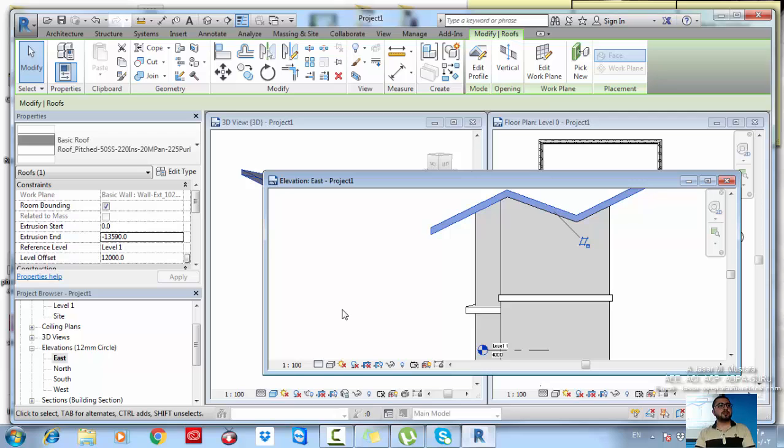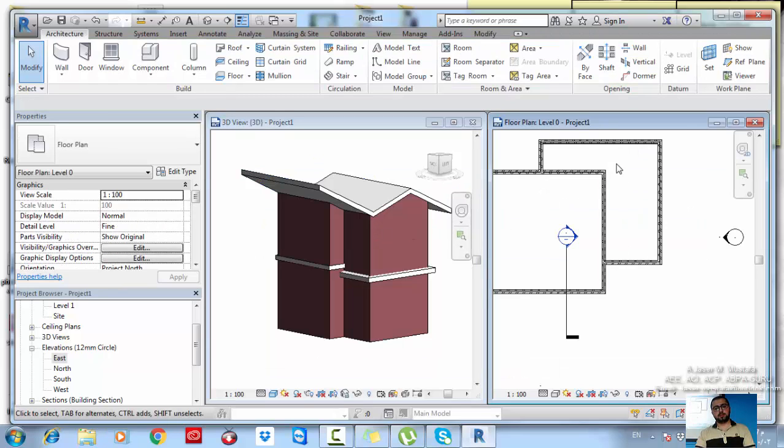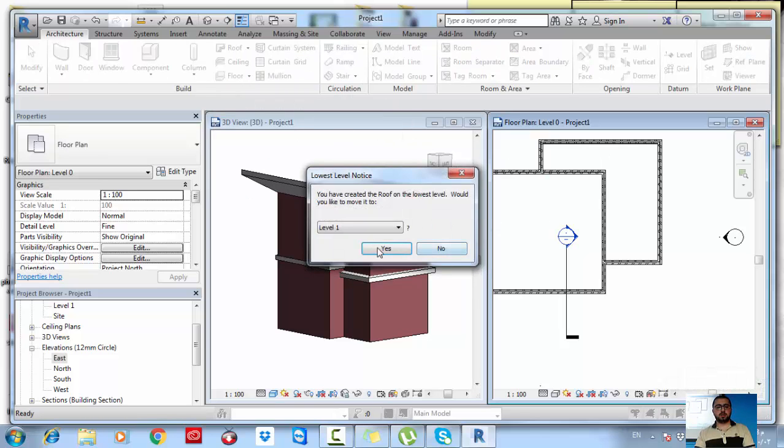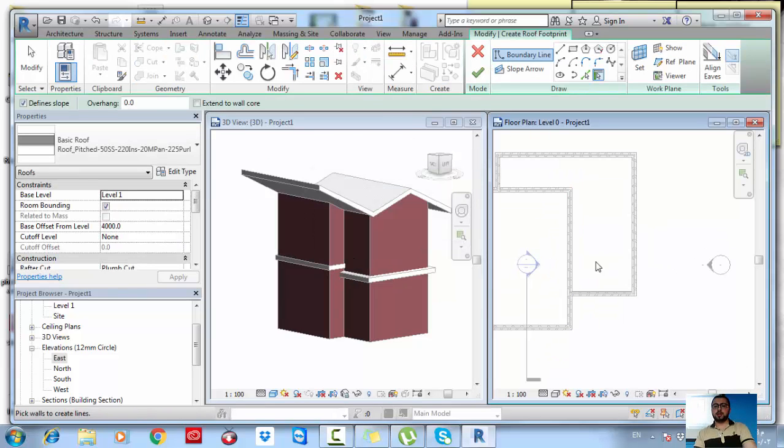Yes. If this 4 angle, I don't want this one with an angle, can I remove the angle? Can you draw something? You want 3 surfaces inclined and one is... There's here on your sample before, you have this L shape roof. Okay. This one. This L shape, yeah. I want only the slope from all the sides, but here on these 2 sides, yes, flat. You can do that. You can just go to roof, footprint, yes, for example, and you can draw.